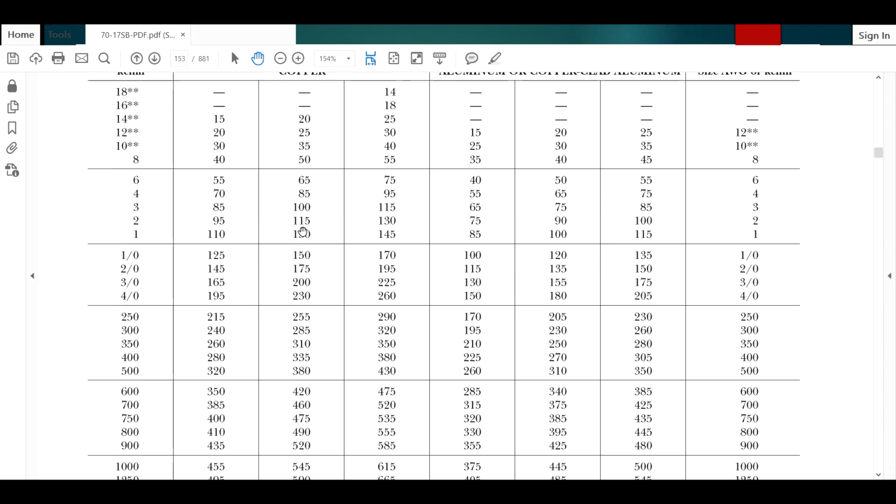All right, so I need a conductor that's at least going to give me 112.5 amps. We're always going to assume copper, guys, unless we state otherwise. So here it looks like I'm going to be at 115 amps. That's a 2 gauge. So I'm going to write that down, 2 AWG. And again, always assume copper unless expressed otherwise.